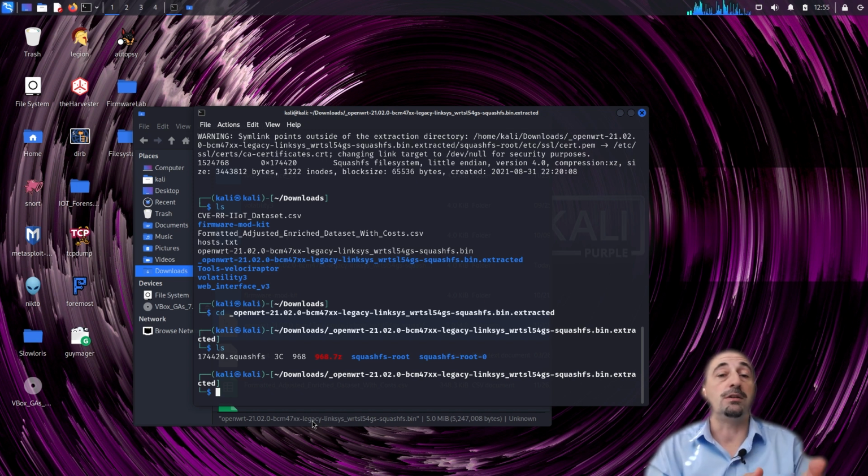It depends on the device. This would be the typical firmware that we would be investigating, for example an OpenWRT router, and then we would be able to extract whatever evidence and leads we are following for this investigation. So you would pick a source, download the firmware files to your workstation, and then engage using binwalk on Linux. That would be one thing, or hexdump, which would be one tool that allows us to view the raw binary data.